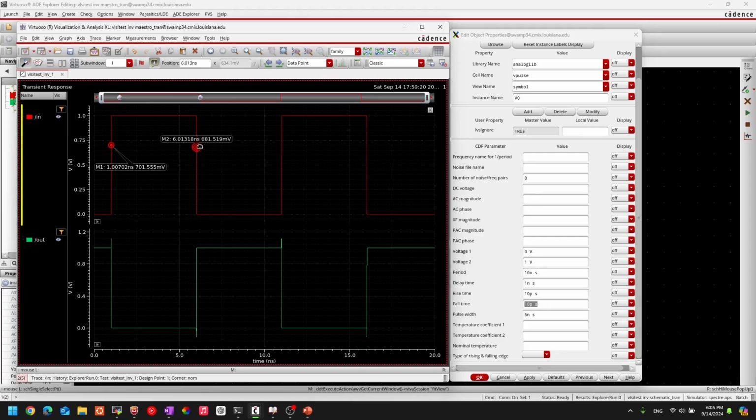So this is called a marker. In order to put this marker, bring the cursor to whatever you want to measure, and then press M. And this will put in a marker. Another good tip is to put in a horizontal line.